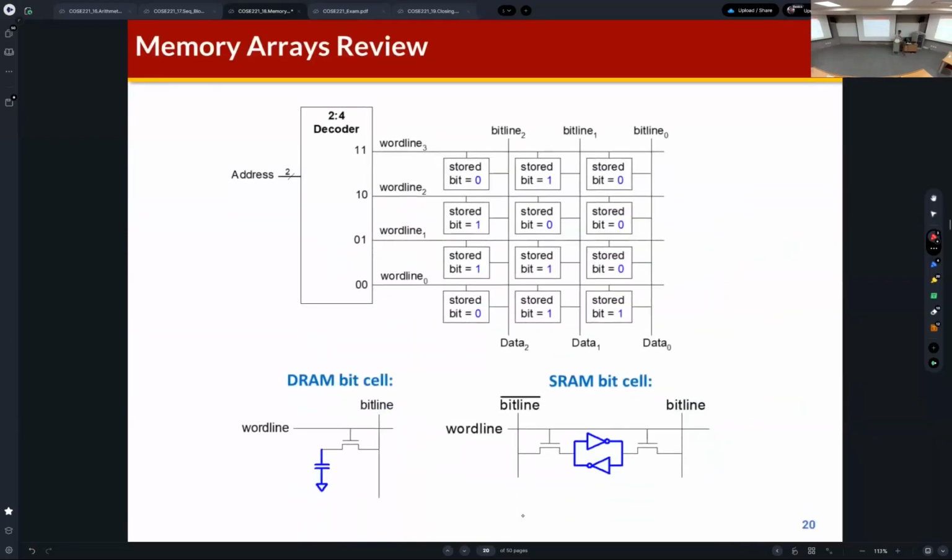I said only this is the different part. Then why do we use DRAM instead of SRAM? As I said, SRAM is more stable than DRAM, and also we don't need to refresh data inside of the SRAM because the electric charge level is maintained inside of SRAM. Then why do we use DRAM as the main memory of the computer system?